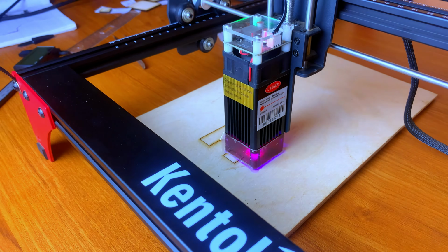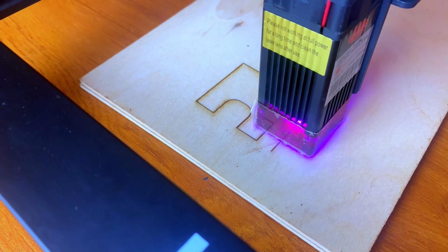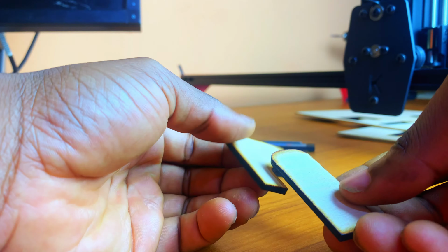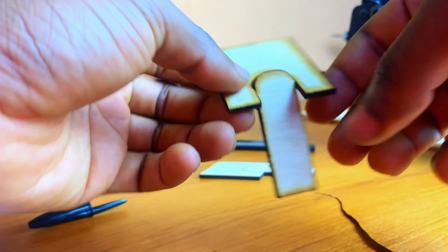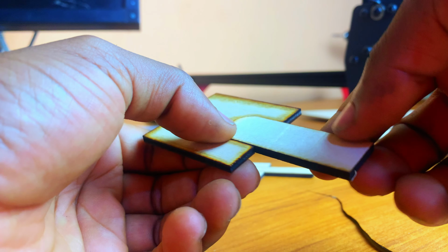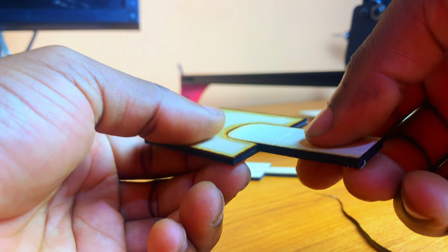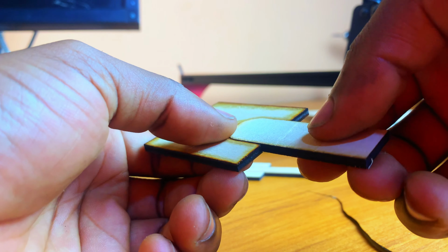But to show the problem we are trying to avoid, I did one without making any changes to compensate for the kerf. And as expected, the fit was no good. The space was just slightly wider than the piece it was receiving, a common problem which renders your cuts useless. Now that we have highlighted the problem here, let us see how the kerf value would help us fix this.